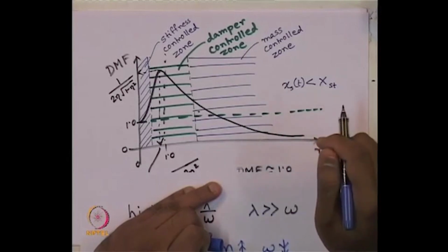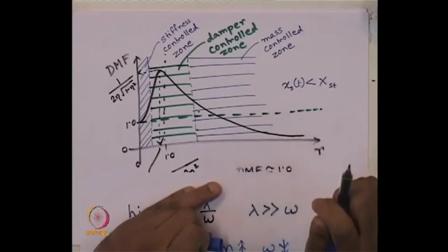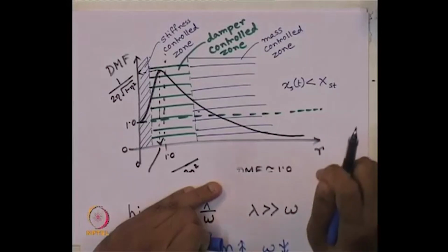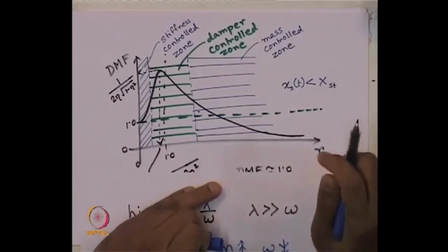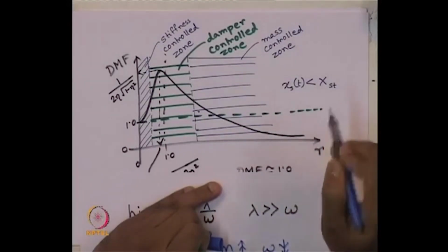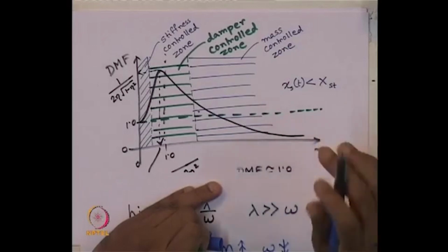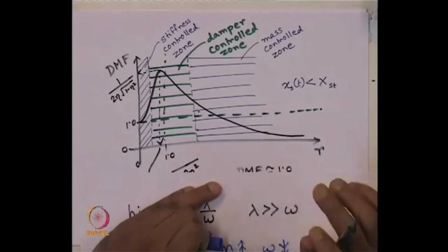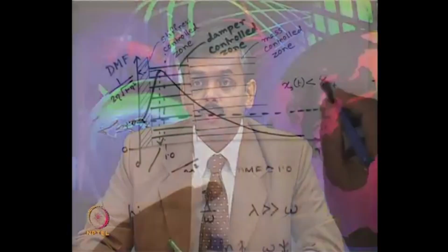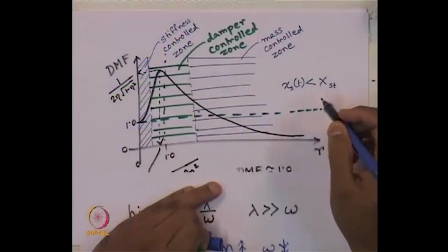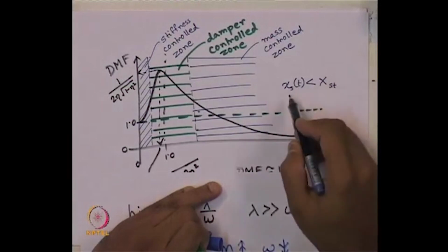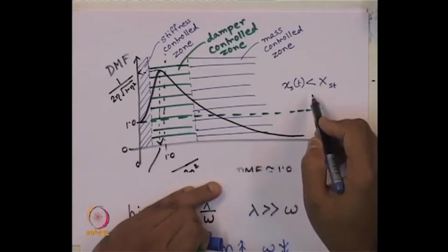As a designer, if you have designed your system or the foundation to take care of static load only, it is sufficient enough to withstand the dynamic load. Correct? Because the maximum displacement it is going to experience is the static displacement, since its dynamic steady state displacement is much less than that.